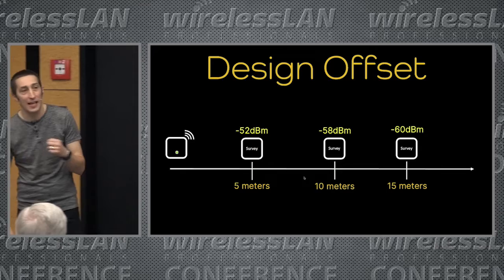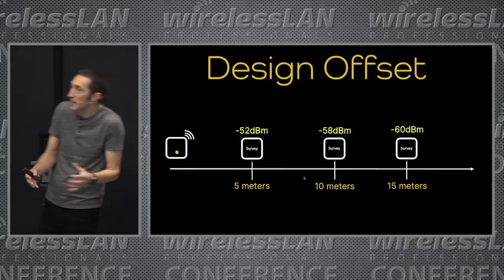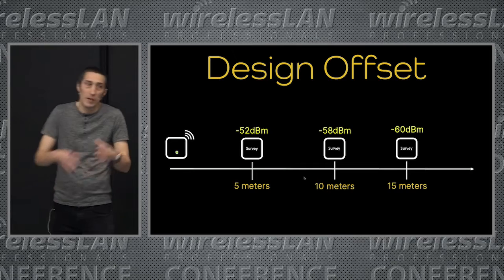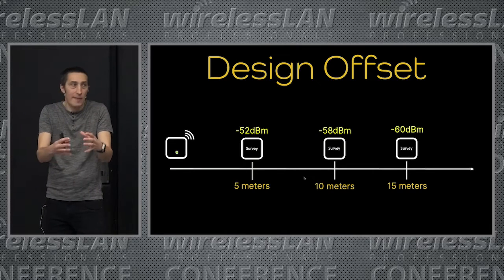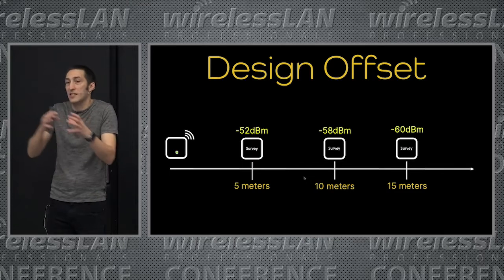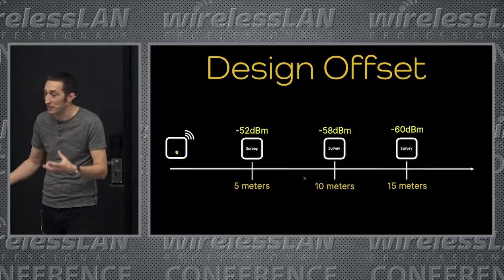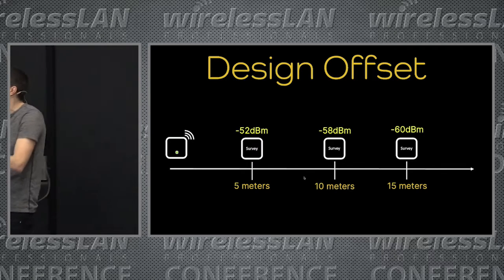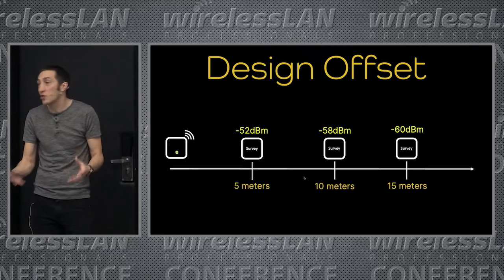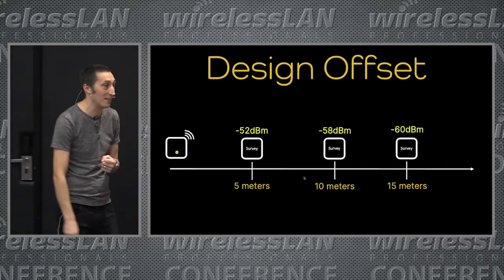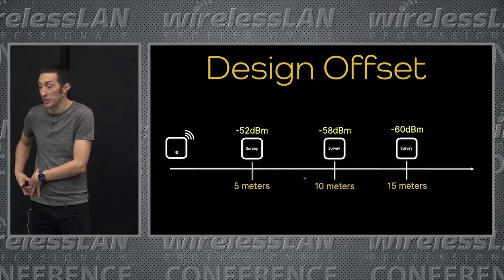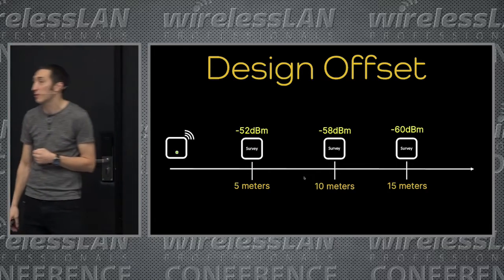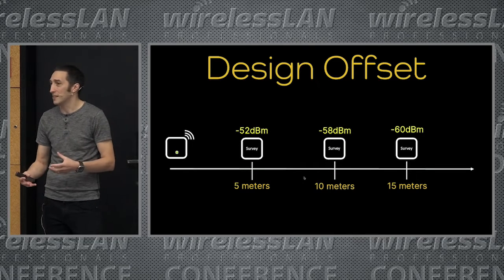The other key to this, obviously the survey device has some inaccuracies. The best survey devices are going to be really, really consistent, but how do you wear it? If your body gets in the way, then when you're taking these readings, you want to try and have the survey device in the exact same orientation, in the same position as it's going to be for when you're going to survey. So think about that, whether you're wearing it on your side, sticking it on your head, or strapping it to a big pole and walking with it in the air, whatever you decide is the most accurate measurement. And generally what I would say is do some testing with your survey device as well. Maybe wearing it on your side isn't very good, because you walk this way and you measure one set of results, you turn around, now your body's in the way, and you get a different set of results. So try it in different places.